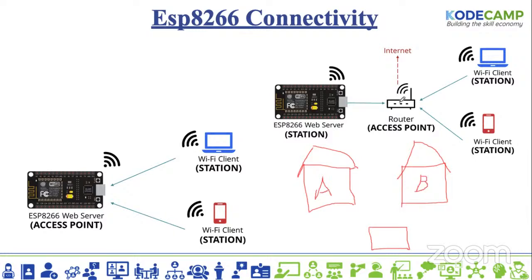I'm using MQTT. So once I talk to my phone, it uses a connection whereby you publish and then you subscribe. Any device that is not subscribed to that particular topic just doesn't hear what I'm saying. But any device that is subscribed to that particular topic listens to what I'm saying, and can take an action.